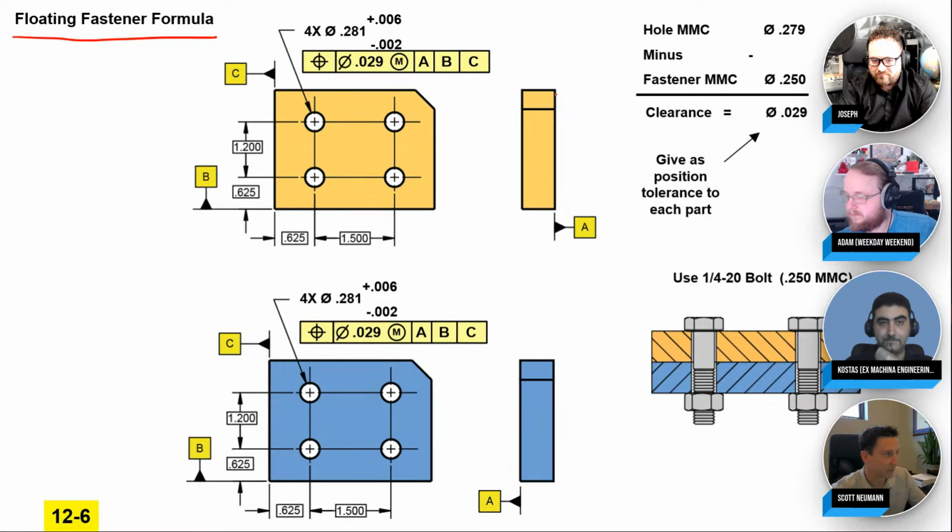Well, easy datums on this one again. So just those edge datums. Again, hopefully they're functional. And that's for another video of picking functional datum features there. We have basic dimensions. I'm going to do inches this time. So 1.5 inches, .625, .625, 1.2 inches. And then the same thing on the other part. They pretty much match. You got A, B, C. And all the dimensions are lined up perfectly in the LibreCAD system there.